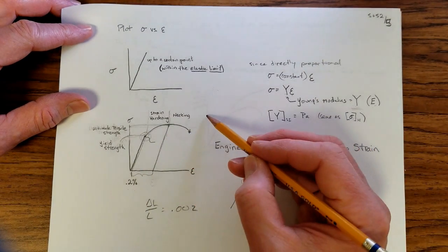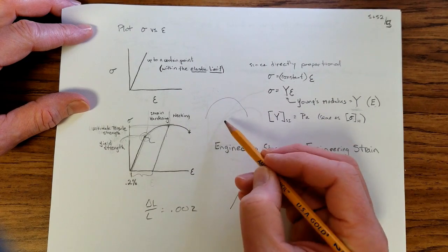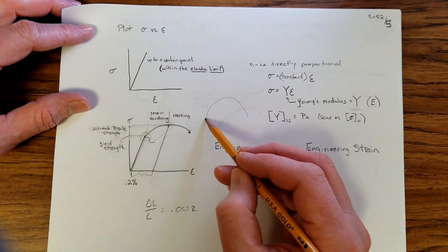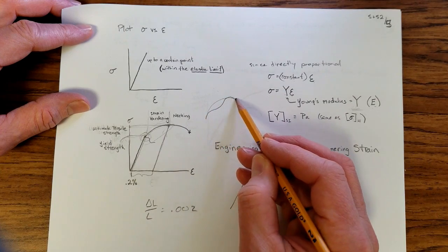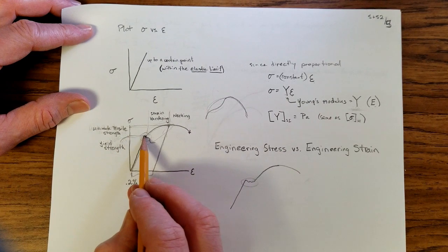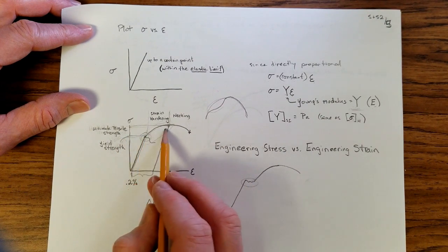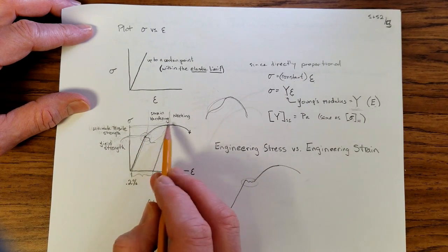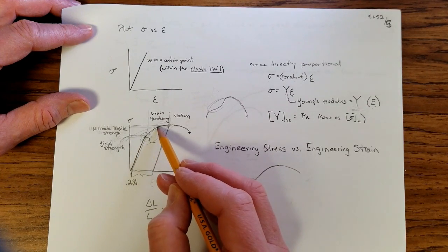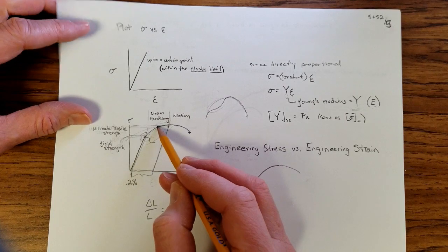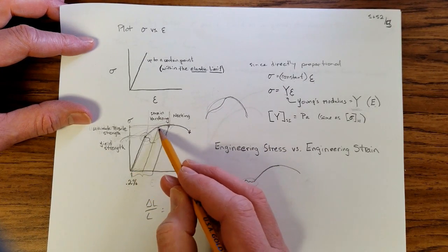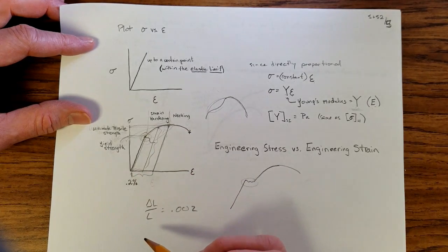So if I have the arch that kind of looks like that, if I did not strain harden it, then there's a higher likelihood that the thing might twist if you exceed the yield strength. But now it requires more to get to the ultimate strength, and so that would be an advantage. But wherever you stop, so if I'm taking a metal and I'm pulling on it, if I stopped here, this would be sort of the permanent strain, and this would now be the new elastic region.